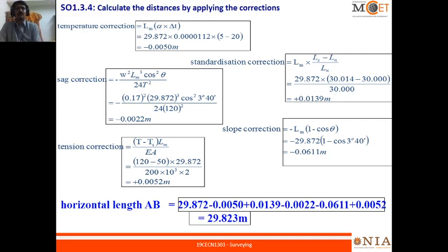For this much accuracy we have to calculate, sir. If it is continued for thousands of meters, what will happen? Listen friends, it will accumulate. In actual terrain, if we use the chain for kilometers of distance measuring, while starting the chain may be standard, in between it may expand, after a time it may contract, right?